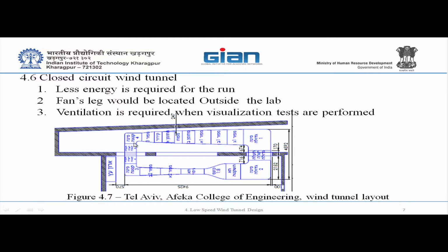Then there is a possibility again to have a diffuser between the first corner and the second corner, but cost-wise and design approach, you would like this to be constant, so you have two identical corners and turning vanes. You don't have to design twice, and you don't have to pay the manufacturer for two different elements.